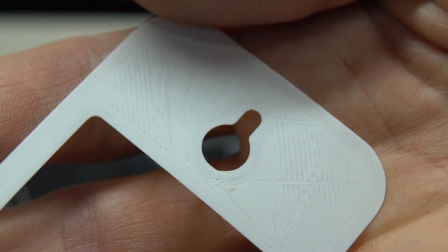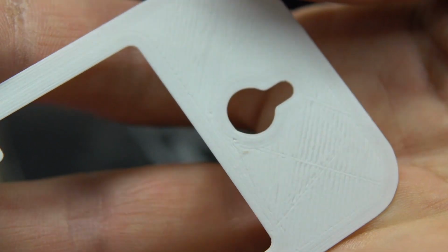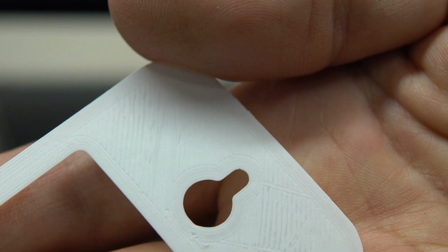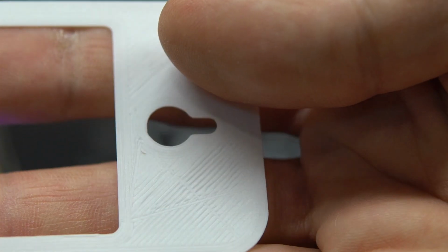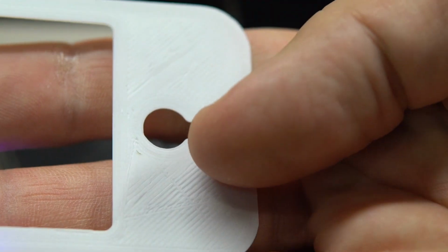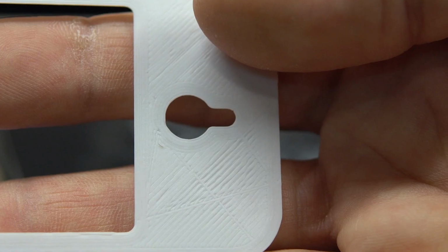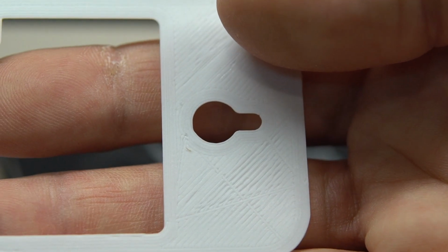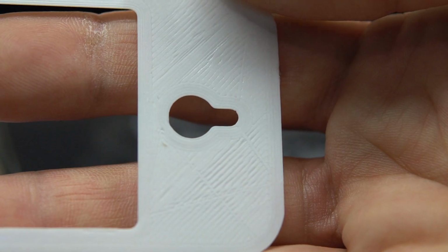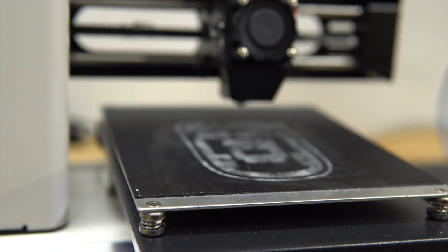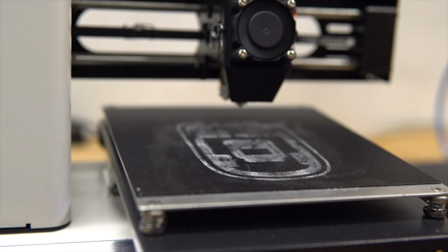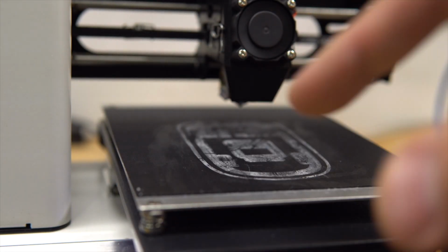You see the lines. So the lines are squished down. I would say it's a bit much, just a little too much, because in some places you don't see the lines. So the extrusion tip is really near. Yeah, let's keep it that way and do the print again.